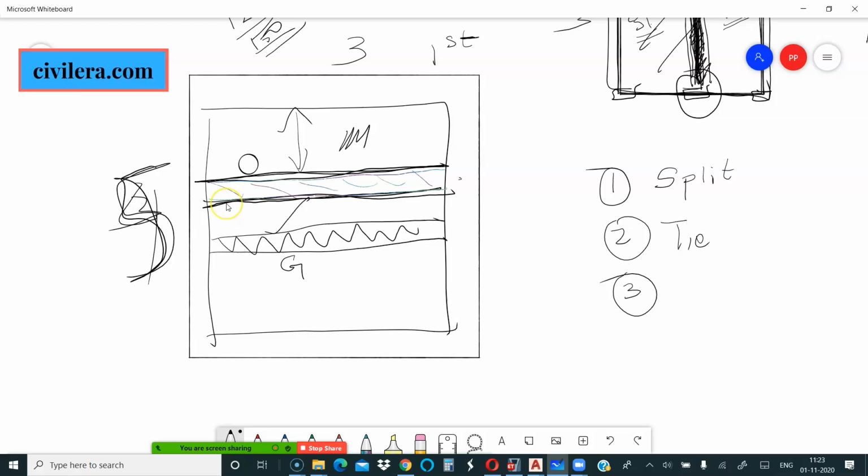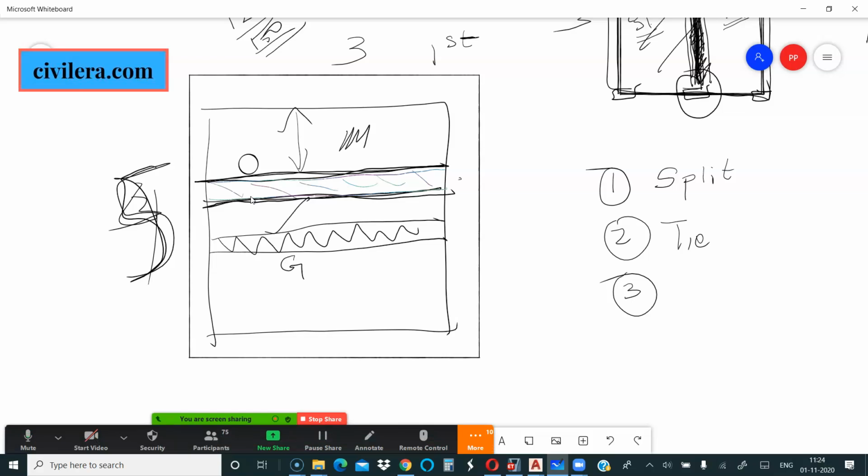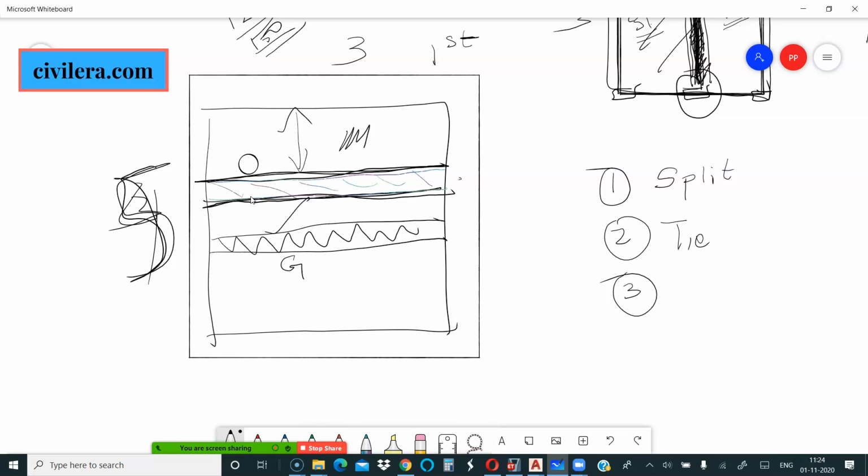So when you scheme a building, from your perspective, you need a beam where you have a wall on top of your slab. And keep in mind that client and architect, and even if it's your house, you will be okay if the beam aligns with the lower level wall, so that the beam is tucked inside the wall. So cut a balance between that. If you have a typical floor, you have no issues because all the walls are in one line. You can give beams everywhere you want.